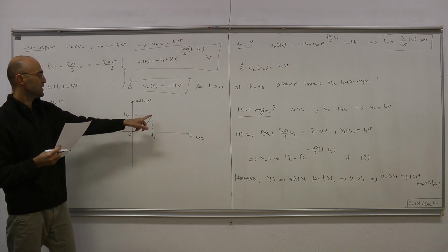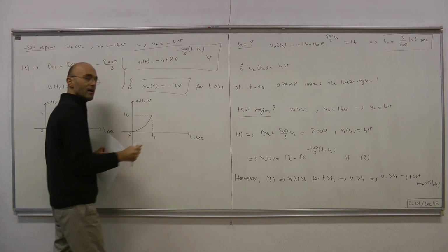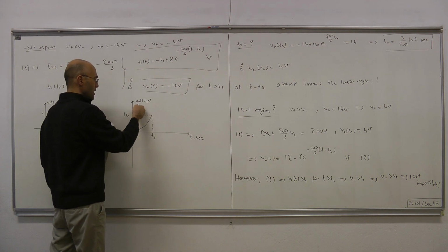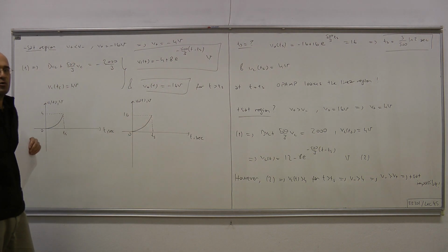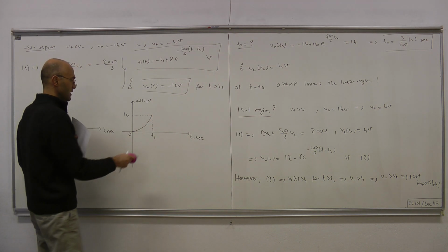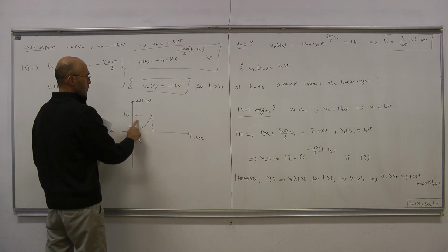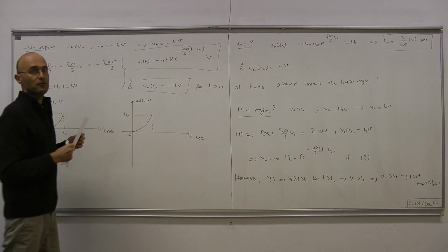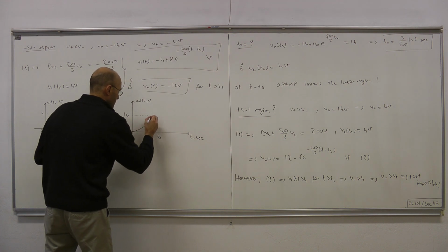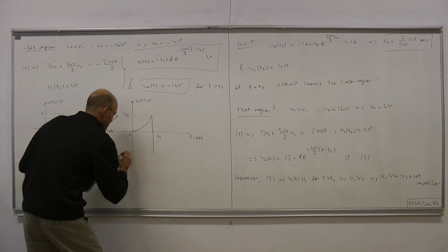Then what happens? We consider whether the op-amp can remain for a while, at least, in the positive saturation region, and we saw that that's not possible. So the out cannot remain at plus 16 volts for any time. And it cannot remain in the linear region. So we figured that the op-amp has to move to the negative saturation region. So that means at Ts, the out voltage hits minus 16 volts.